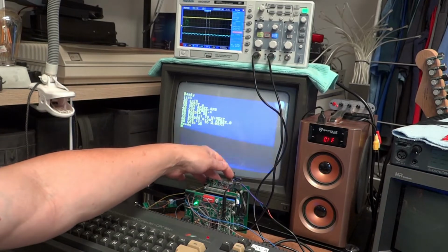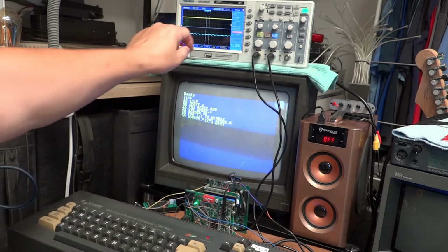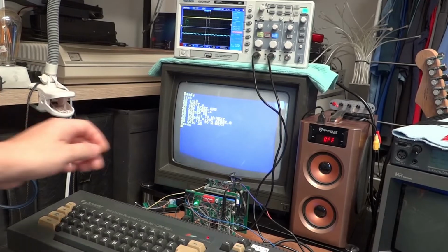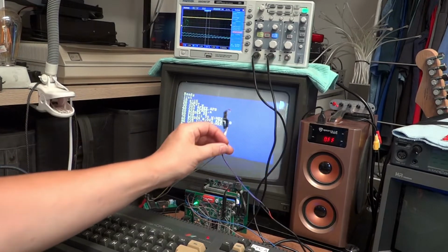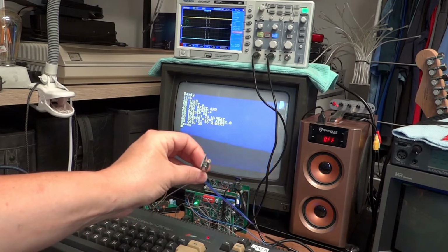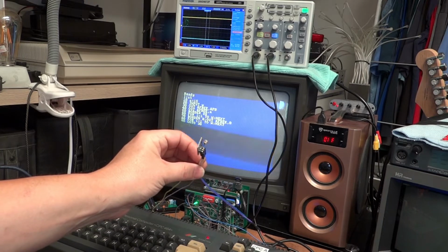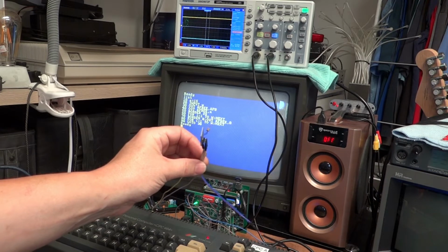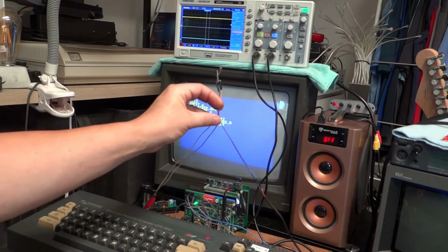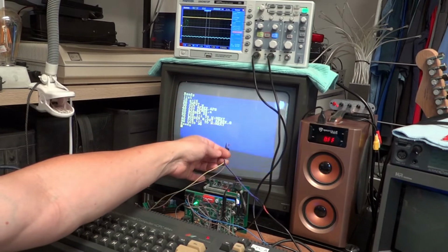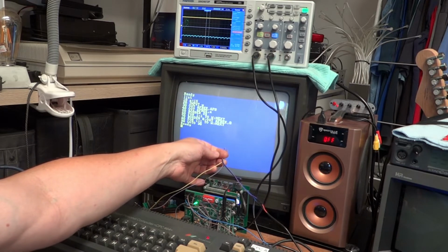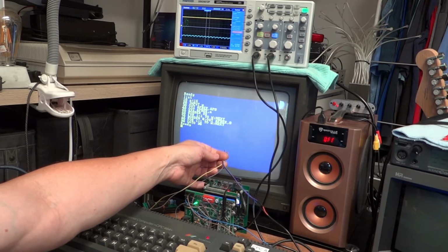Then on channel 2 you can already see a signal here, the blue line, which is a photocell, a photoresistor. This is picking up changes in brightness of the screen. When I change the color, you'll see a signal here, and you can already see that it's picking up the 50 Hertz signal from the screen.